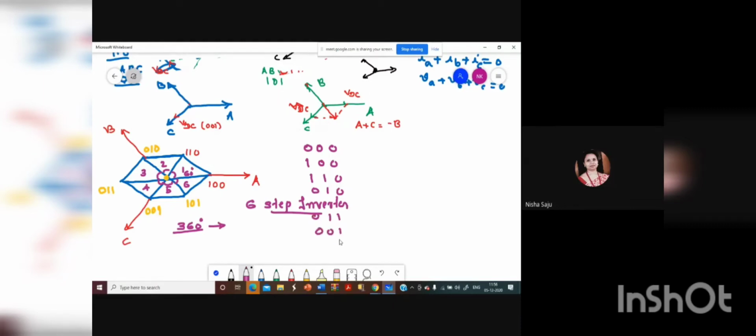Again, it will be completing like this. So this one means you will be having 0 level, because at the center it will be 0 level. In 1, 0, 0 means that is in this direction, right? So we can mark this as equal to VDC into e raised to j into (n minus 1) into pi by 3, where n will be varying from 1 to 7.